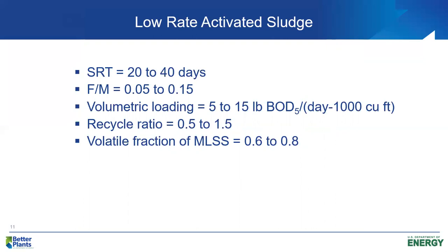Now, we need to keep that in perspective, because even if we have a substantial population of nitrifying bacteria in our biomass, they will generally only be about 2 to 4% of the overall bacteria in the process. The heterotrophic bacteria are BOD removing bugs, carbonaceous BOD removing bugs that use organic matter as a carbon source.